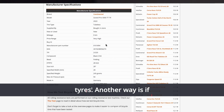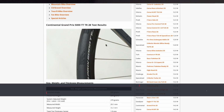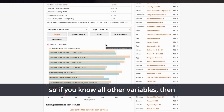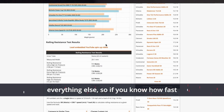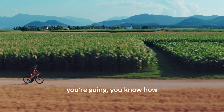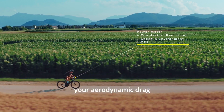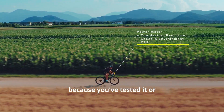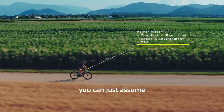Another way is if you do have all other metrics, so if you know all other variables, then you can estimate CRR based on the fact that you know everything else. So if you know how fast you're going, you know how much power you're putting out, if you know the conditions, if you know your aerodynamic drag because you've tested it or you're testing it with something, then you can just work out what your CRR is.